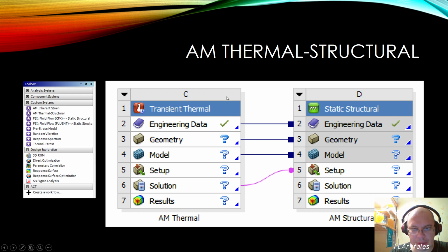We create a thermal analysis, and then a structural analysis, and we can obtain the strains and stresses that will be present at the end of the printing process. When using this printed construction, it will have pre-stresses and strains, which exist before use, but as a result of the additive manufacturing process we get those strains after printing.